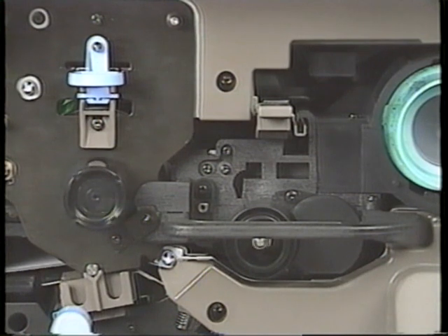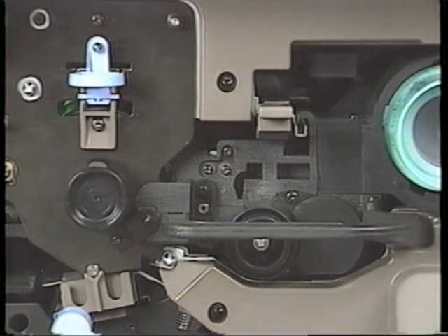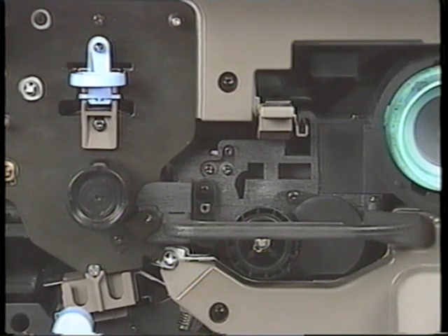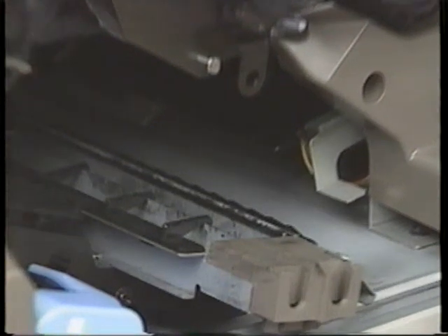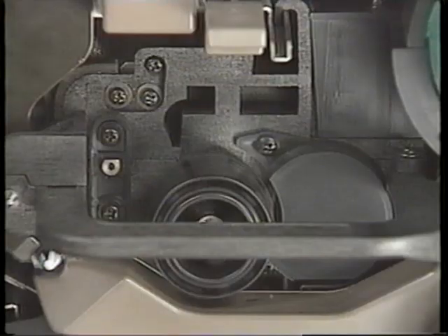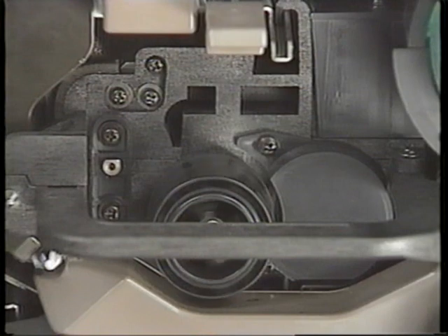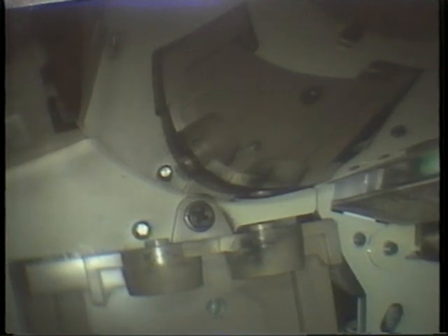The development system has to maintain the proper ratio of toner to carrier with a high degree of accuracy. If a copier is running with too much toner in the system, it can contaminate the inside of the machine like fine dust. To maintain copy quality and keep the machine running clean, most copiers have a system that monitors the concentration of toner in the development roller's magnetic brush and adds toner to the development unit only when the concentration falls too low.